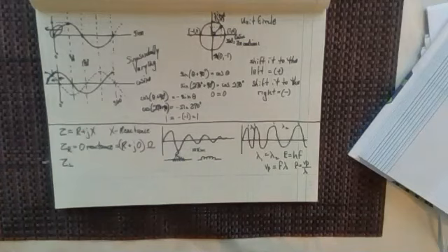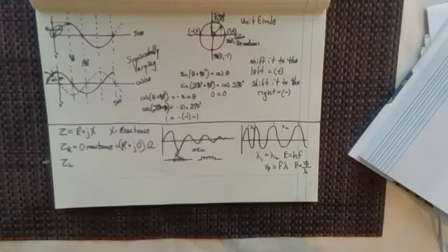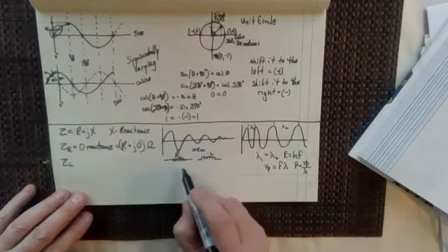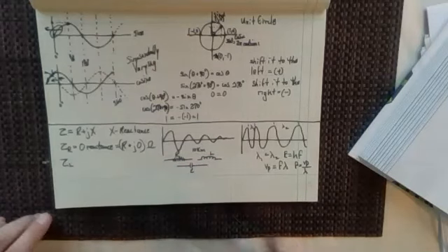That's to help with the magnetism, because the high permeability of electrical steel allows a greater magnetic field to be created by the inductor instead of having a hollow air core. The difference in relative permeability between electrical steel and air can be almost 10,000. So, that's an inductor anyway. And then, of course, the capacitor, which is two plates, and that's very descriptive of what a capacitor really is.